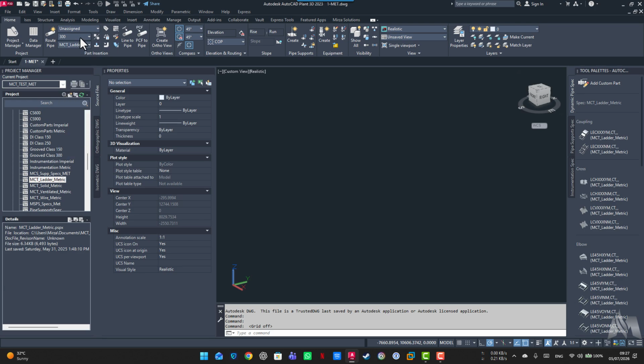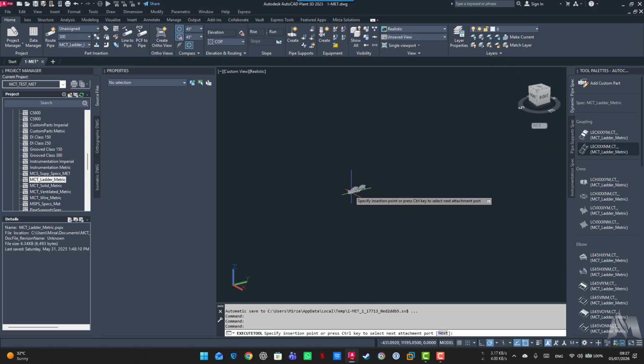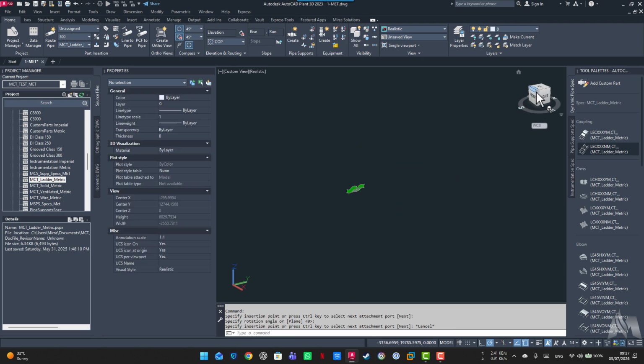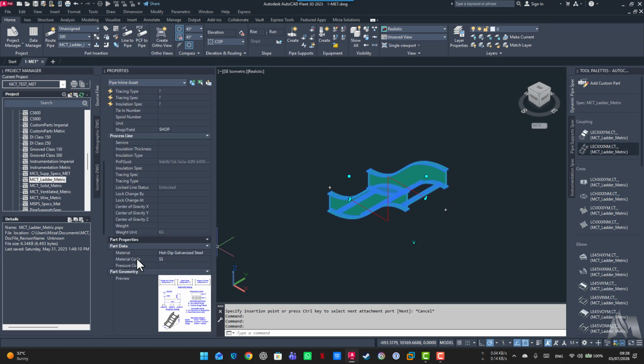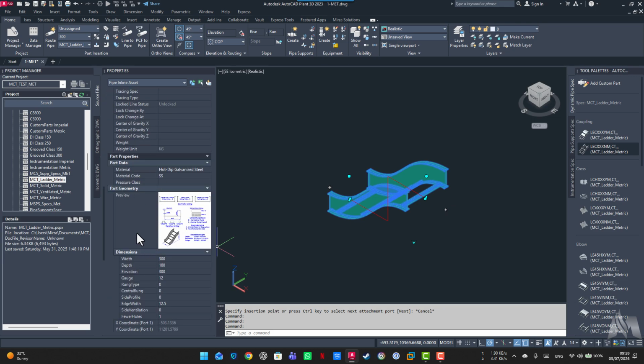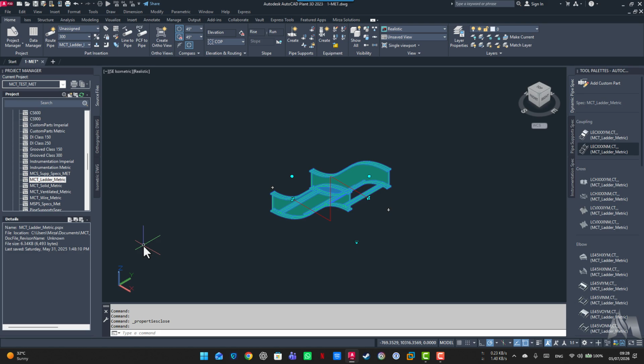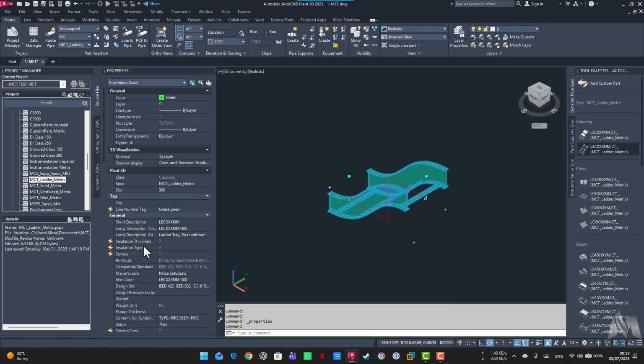So in parametric cable tray plugin, the insertion of each cable tray component is very simple. You simply click the desired component from the list over here. You place it, orient it, and then simply click on it. And the component is placed. Once it is placed in the model space, after that you can change its parameters. Go to the property palette. If you are not already there, press Control 1 on the keyboard and it will pop up.